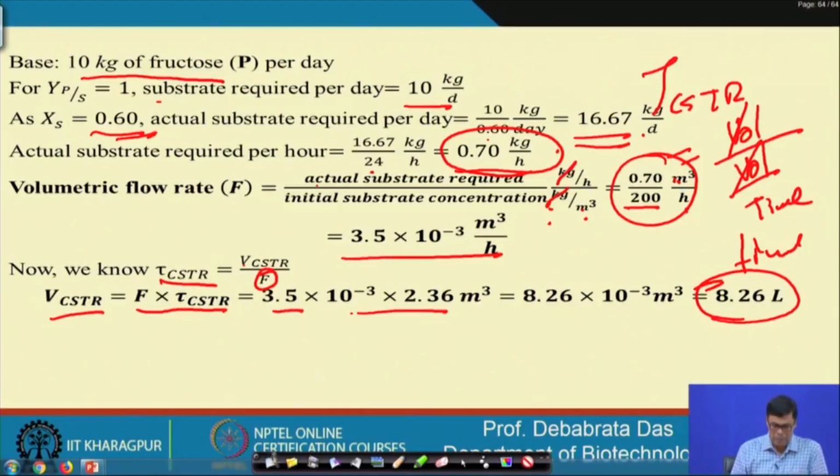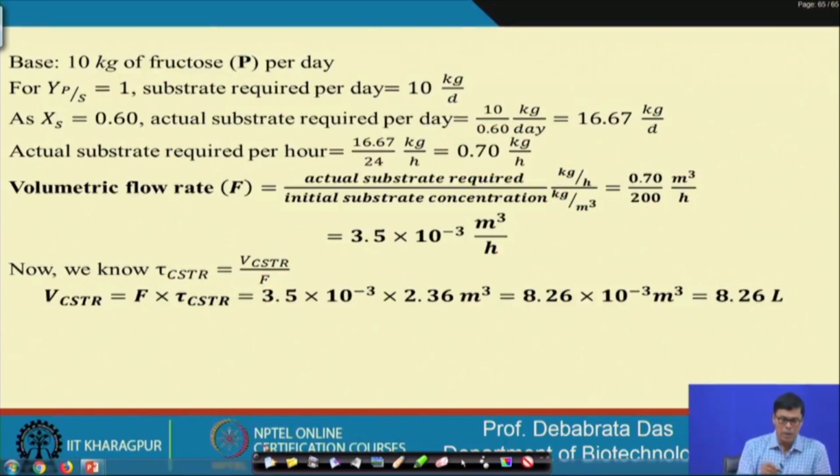Again, I am telling you how we have done this. Initially we consider 10 kg of fructose per day, and we take the yield coefficient from the stoichiometry to find out how much substrate is required for producing this much product. From the stoichiometry, 10 kg product formation needs 10 kg substrate, but your conversion efficiency is 60%, so you divide by 60 and find the exact amount of substrate required per day. Then you find out how much substrate is required per hour.